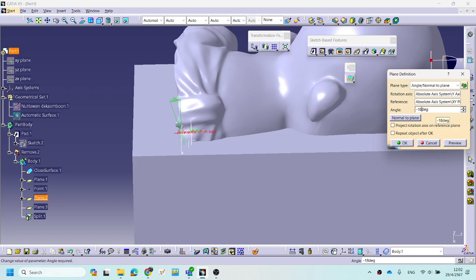Because you just avoid the touch area, and the touch area may be the cutting edge, and the cutting edge is not enough for the depth of the workpiece, right? You avoid that by using the draft angle. The cutting tool touches at the point, and you can avoid too much force.